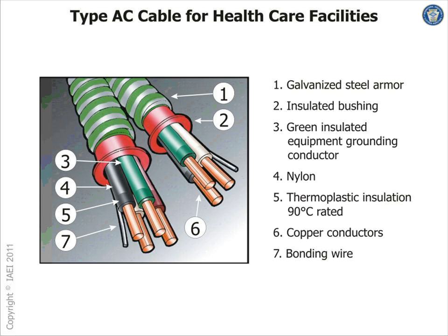In the patient care areas, you have to have two grounds. One is a fully insulated ground, and the other one is the shield or another ground, like in this case, two cables. But right at the receptacle in the patient care area, you have to tie the insulated grounding conductor and the other conductor together. That's why it's not really an isolated ground system.